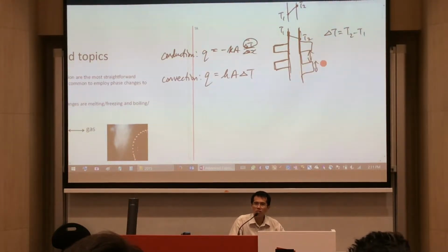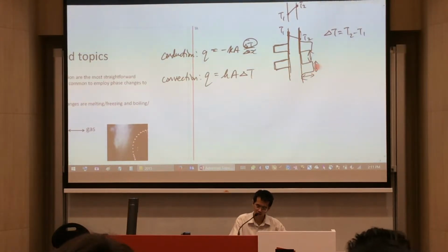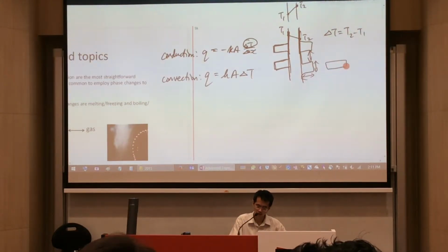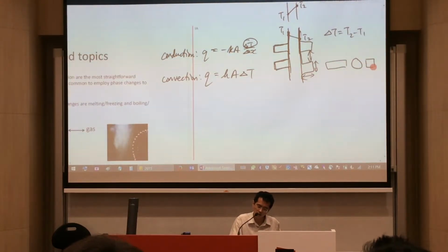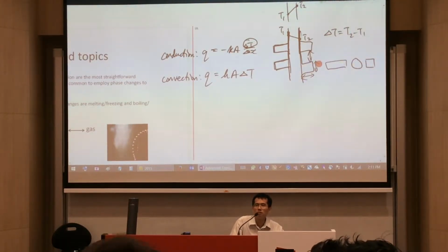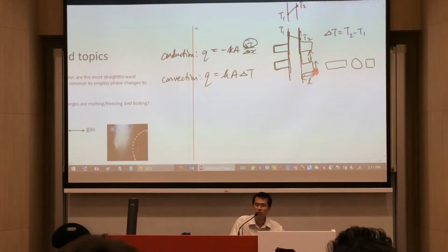There's a good thickness of fin by the length of the fin that will come into play. And different shapes, types of fin. This one might be a cross-section that's rectangular. This one might be a cross-section that's kind of like cylindrical pins coming out. It might be a squarish cross-section. Different cross-sections will offer different surface areas. Okay? But then one important criterion is this length over here.